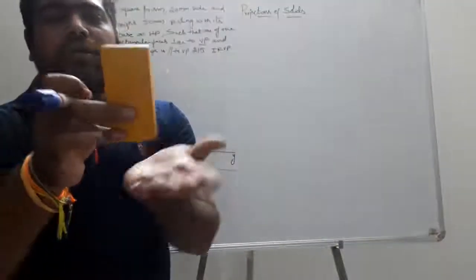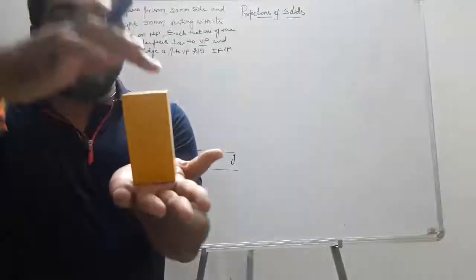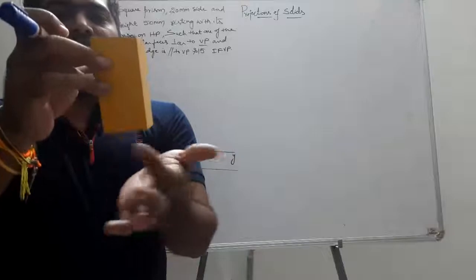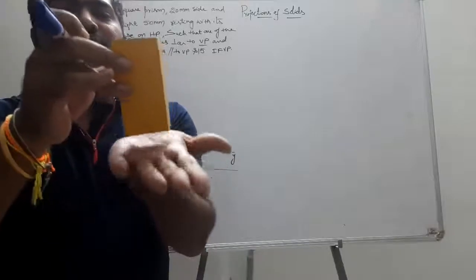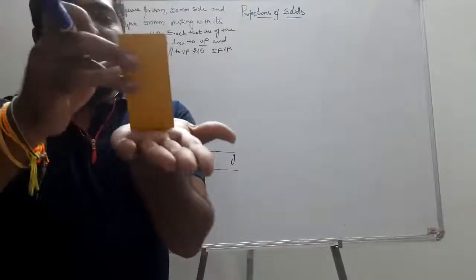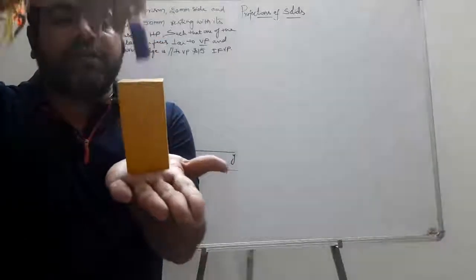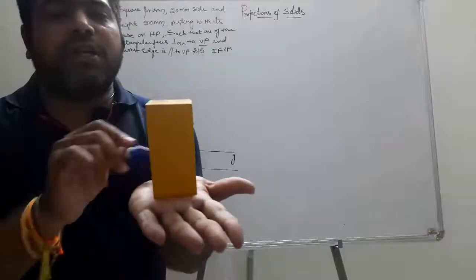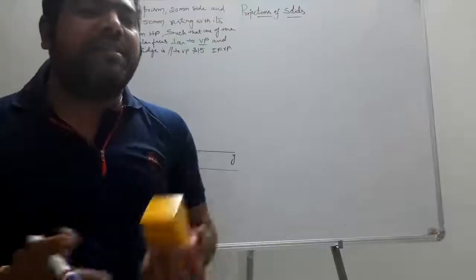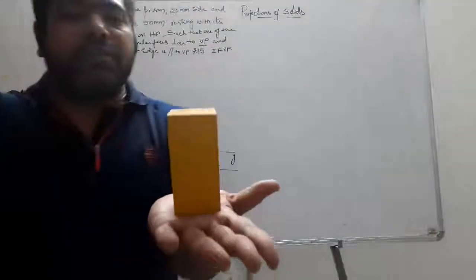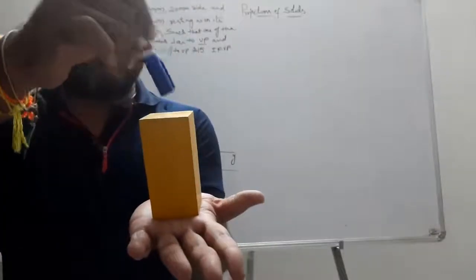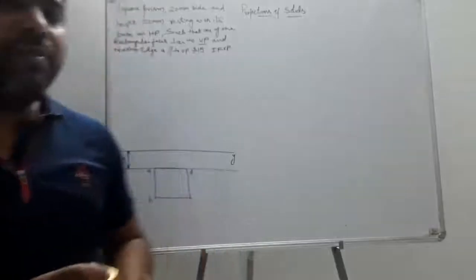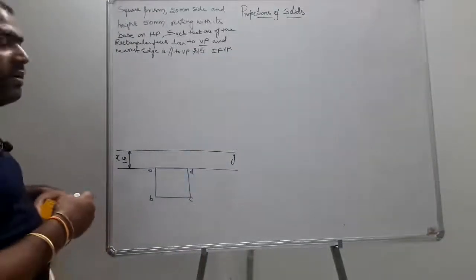One and two. If you see from the top, this base is visible, that is ABCD, let us consider it as visible. Then PQRS is invisible, which is going to be resting on HP. When you see from the top, these four corners are visible, bottom four corners are going to be invisible but existing. So while you are going to see from the top, these four corners are represented with the visible points, bottom four are going to be invisible. So I put those points in brackets.